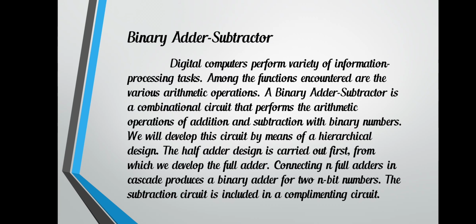In a binary adder-subtractor, a digital computer performs a variety of information processing tasks. Among the functions encountered are the various arithmetic operations. A binary adder-subtractor is a combinational circuit that performs the arithmetic operations of addition and subtraction with binary numbers. We will develop this circuit by means of hierarchical design. The half adder design is carried out first, from which we develop the full adder.